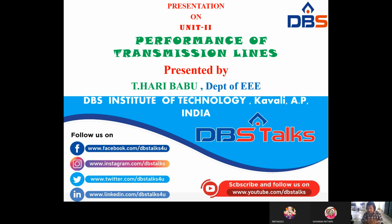By using these three equations, we have to combine, rearrange and substitute. We are getting the ABCD parameters of the Nominal-T method. What are the ABCD parameters for the Nominal-T method? A is equal to D is equal to 1 plus YZ/2. B is equal to Z into 1 plus YZ/4. C is equal to Y.